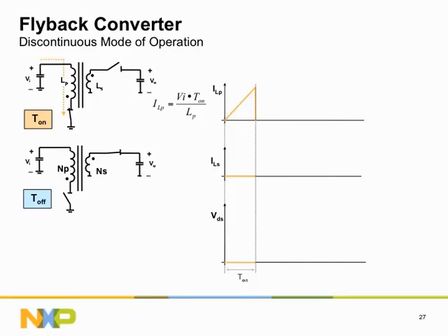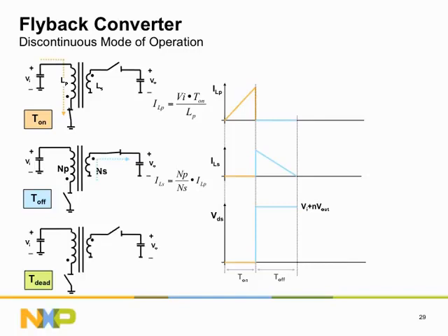The third graph shows another important parameter, the voltage across the primary switch. Of course, the voltage across this switch, mostly a MOSFET, is 0 volts during the primary stroke because the switch is closed. The secondary stroke starts by opening the primary switch and closing the secondary switch. The current that was flowing in the primary inductor of the flyback transformer cannot continue to flow because the circuit is interrupted now. This fall of the current to 0 is reflected in the upper graph.